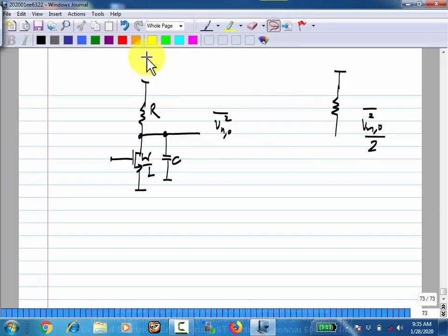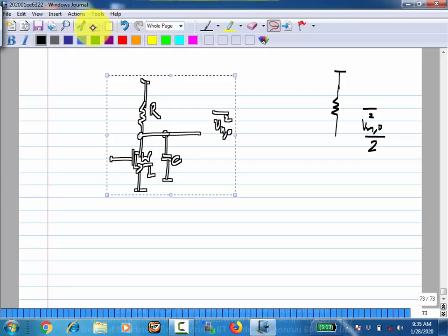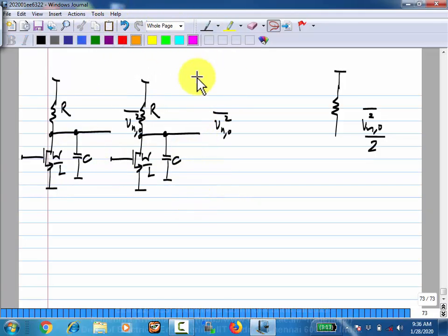So essentially, this is known as circuit scaling, which you will see more of in analog IC design. You take two copies of the circuit and connect the corresponding nodes together. Imagine your circuit is modeled by equivalent current noise sources, which we can do for both MOS transistors and resistors. What happens when you put two of these together? What happens to the spectral density of that effective current? You will have two current sources in parallel. The total current spectral density becomes 2 times, because the two are uncorrelated.